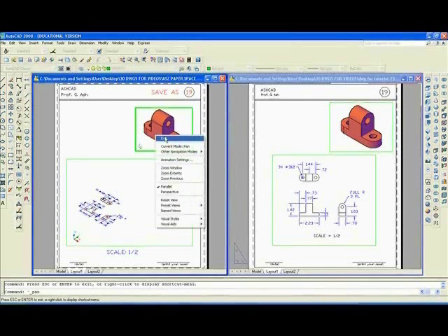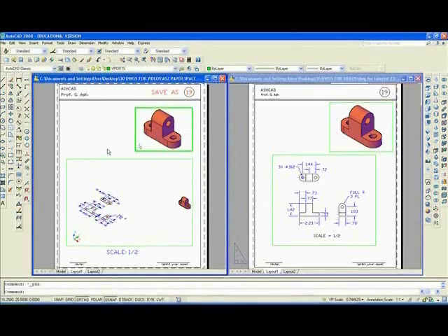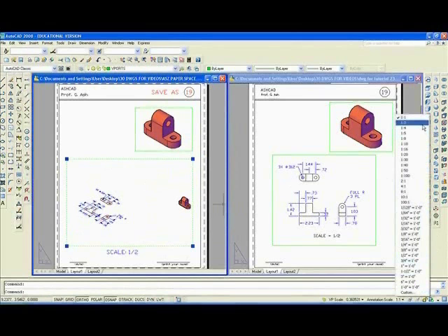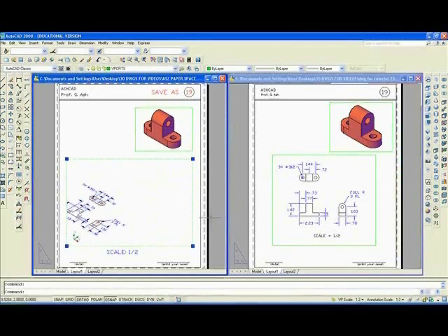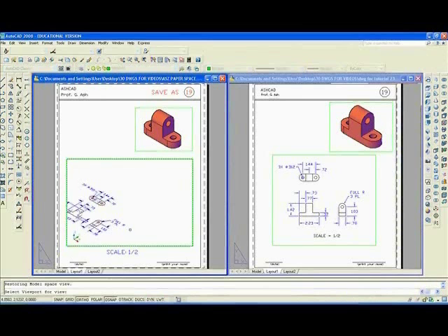And that drawing looks okay. Let's see how the bottom one came out. Click on that, and the scale on this should be 1/2. So I'll go here to Annotation Scale, click on 1/2, click on the top view. Wait a minute, I fouled that up.